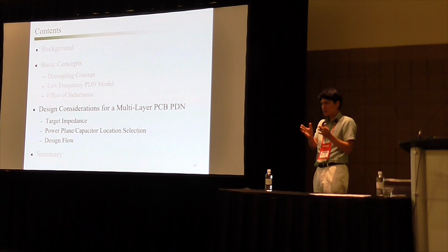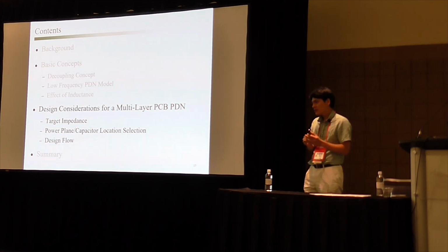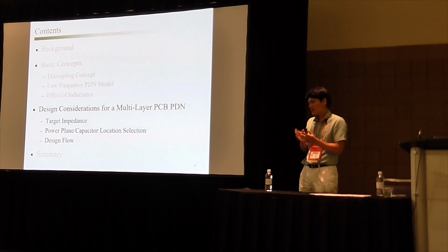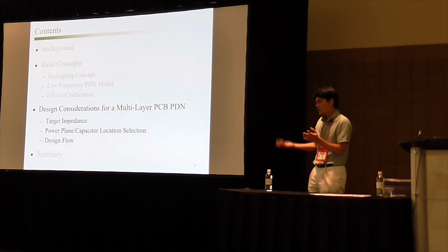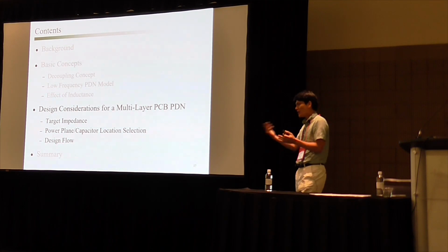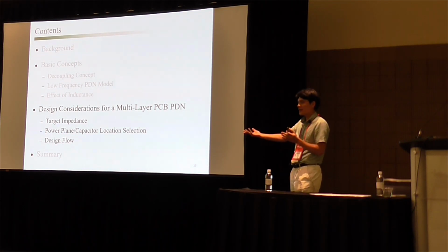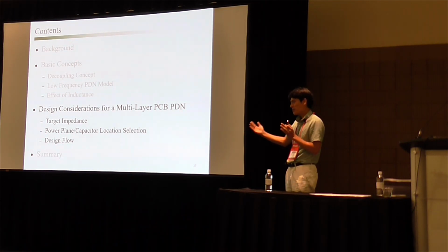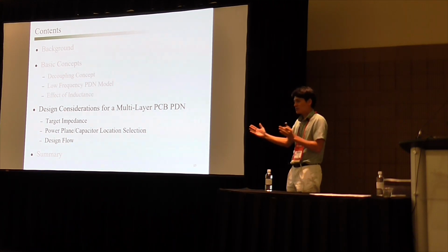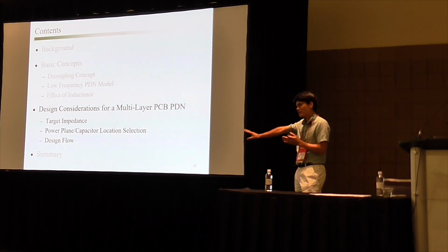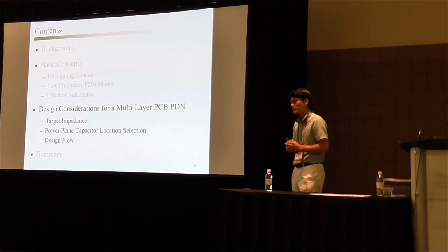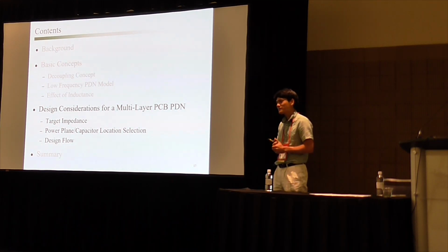So between them, there will be low inductance, and high frequency can be covered by this low inductance path. For lower frequency, we have high value capacitors, but a little bit far away, so between them there will be a relatively larger inductance. So low frequency can be covered by those decoupling capacitors. Did I answer your question?